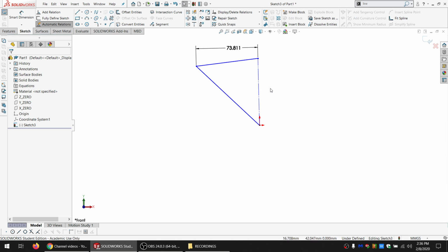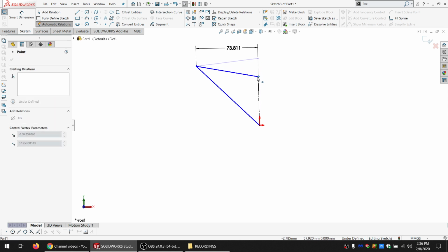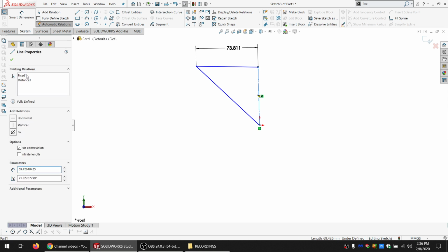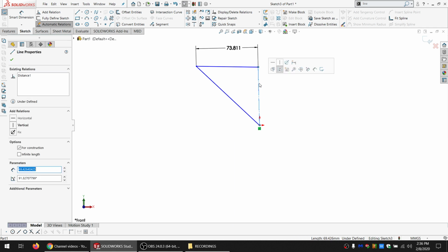unless it's to hold something in place while you do something else, and then you go back to it. And so, for instance, if I wanted to adjust this to be like that without dragging this left and right, I could do that, and then I'd go back and just select fixed in here and click delete, and then the fix is gone. That's the only thing that I'd recommend using fixed for, unless you're doing art, basically. Other things I can do, I can click infinite length, avoid that. It's really not useful for anything that I've found, and it just causes problems.